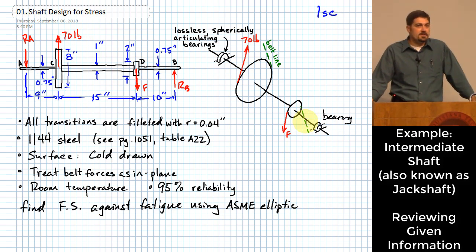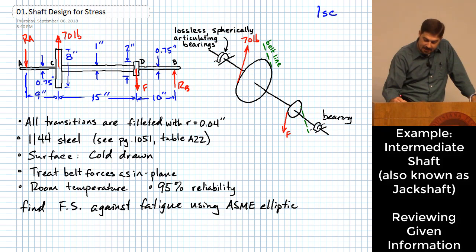In some cases, you will see examples where there might be zero tension on the looser end of the belt or chain. That's what we're going to assume is happening on this one: all of the tension is applied on one side of the sprocket, and that's a 70-pound load applied right there, reacting against that so that this thing rotates at a constant speed.